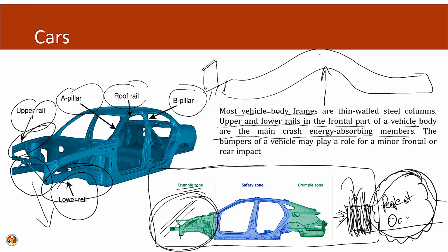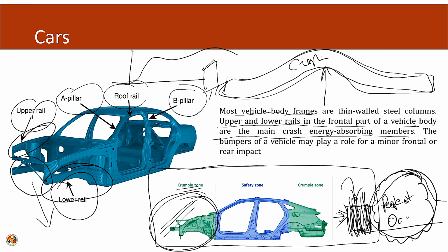This thing we can find equivalent to our crash barriers. The crash barrier is also made up of energy absorbing material having a very large plateau, and the deformation here is also more. The same way our bumper also behaves. So, this way the car is designed to absorb the energy.